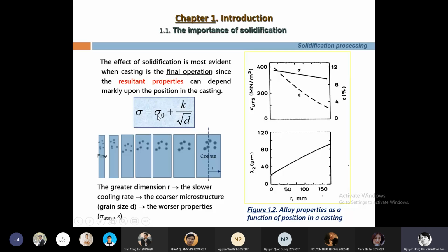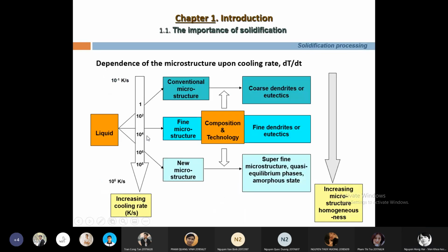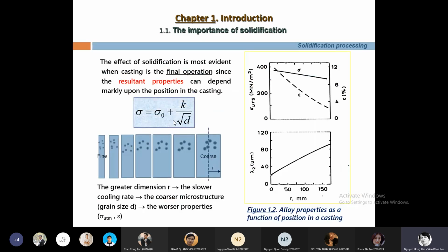So how to create the fine microstructure is a very important question. How to create the fine microstructure? We have the answer here. Fine microstructure: we have to increase the cooling rate and solidification rate. Okay, this is the answer for this question: how to create the fine microstructure to improve the mechanical properties.